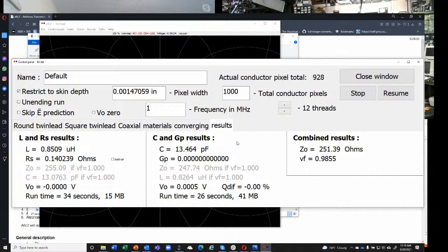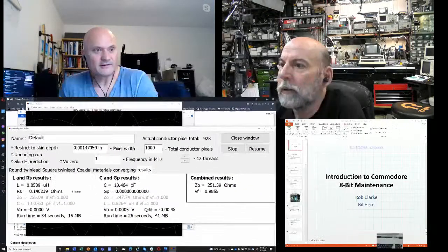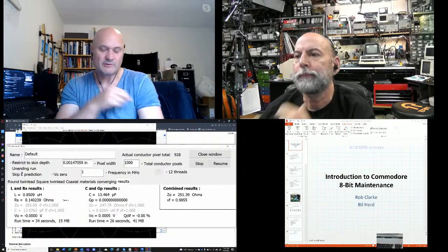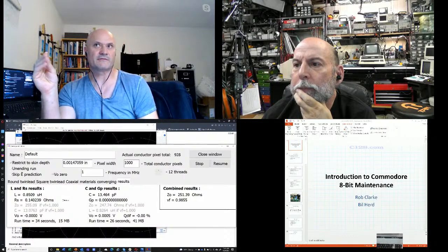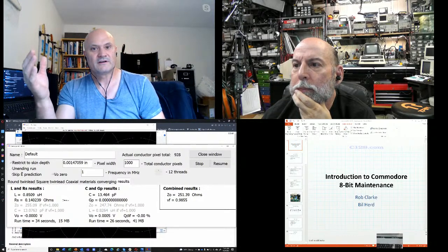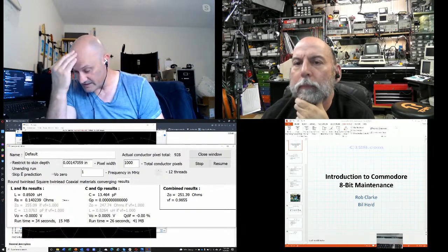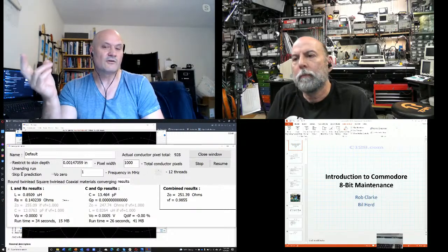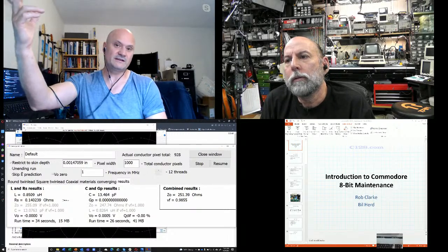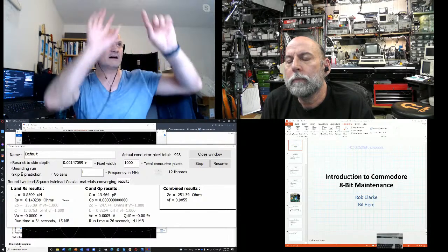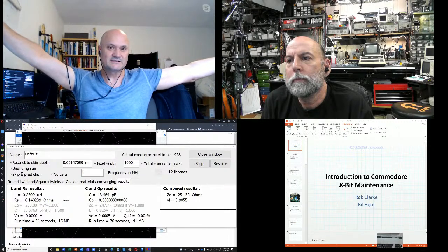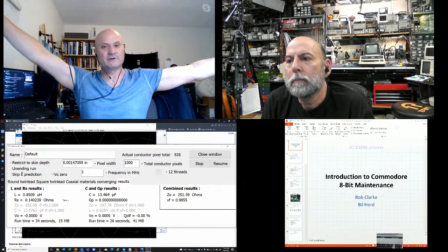And so you can use this to design a transmission line if you want to design a cable or a twin lead. So I guess what a lot of people use this software for is there's a lot of antenna feed lines for HF, shortwave, VHF, UHF ham rigs, and it's awfully convenient to build a twin lead feed for, especially if you're doing HF and VHF horizontal antennas where you have a dipole strung up between two trees or poles.